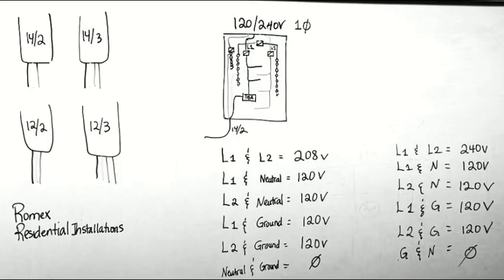15 amps, right? So let's say that the total amperage of the circuit is 15 amps. I'm running a 14 gauge wire, and this circuit has a capacity of 15 amps. Because my amperage adds up in this circuit, I need to make sure that all of these loads don't exceed 15 amps. Because the amperage of all of the loads in a parallel circuit is going to add up.